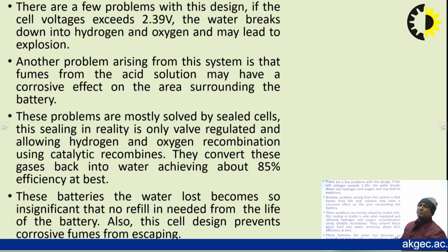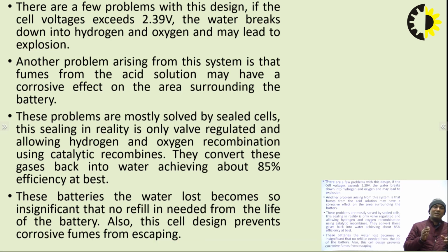Another problem that arises from this system is the acidic fumes. These acidic fumes corrode nearby metallic objects and cause some kind of smell to come from the battery. Okay, so just to remove the acidic fumes, we have to keep the battery in a ventilated area. Another part is that the problems are mostly solved by sealing.